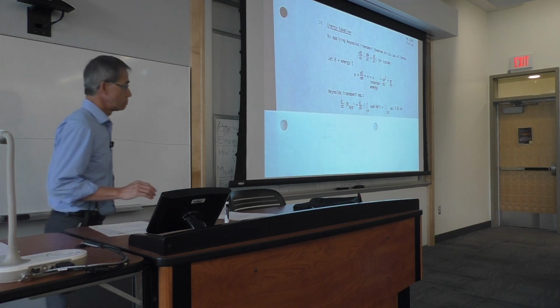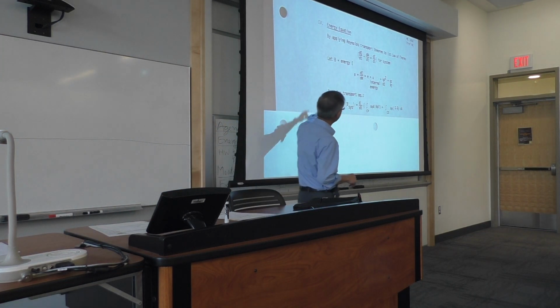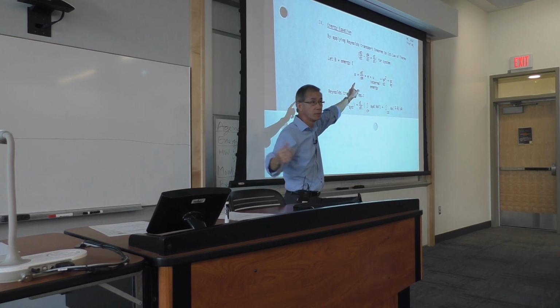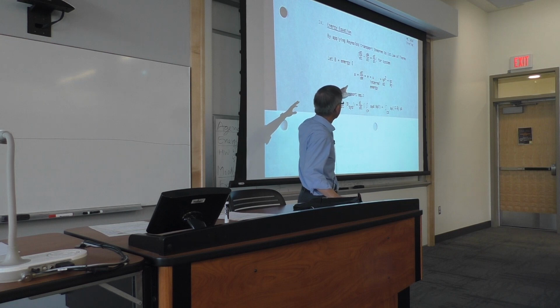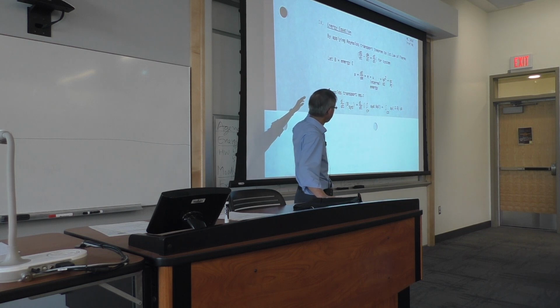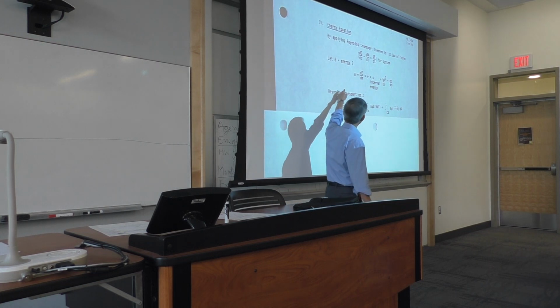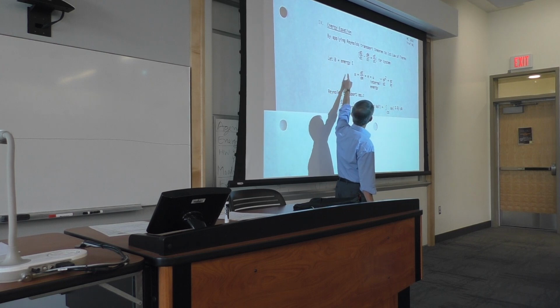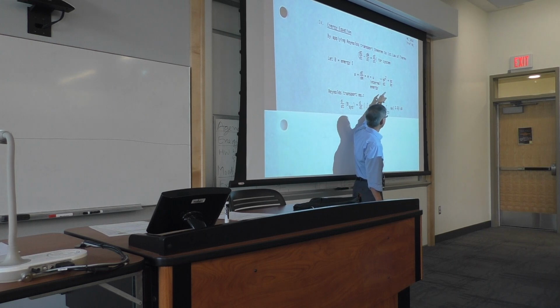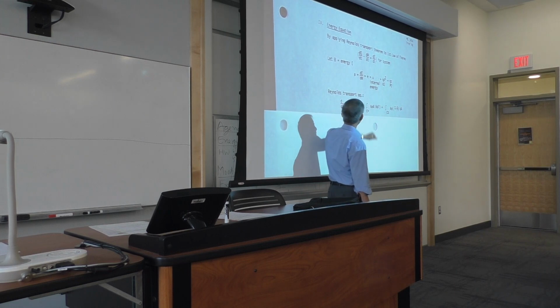So, system equation. What I have done is the equation I have covered by the screen. Instead of just Q minus W equal to capital E, I take the rate equation, which is differentiated with respect to time. Are you okay with that? All right, so I have now a rate equation for the first law, and like I did before, I introduced the capital B to become a total energy that consists of internal, kinetic, and potential, all per unit mass basis.